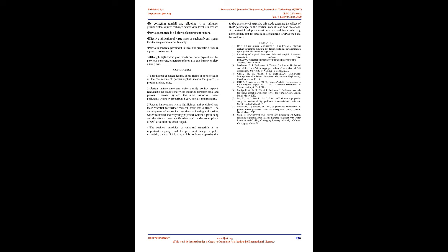Testing methods: the water absorbing capacity, water retention capacity, and compressive strength of hard and water retentive mortar, and the liquidity of the fresh mortar, as well as the rutting resistance, moisture susceptibility, low temperature bending resistance, surface slip resistance, and cooling effect of water retentive asphalt concrete were tested using at least 3 replicate specimens. Objective: 1. To study porous pavement. 2. Planning and designing of porous pavement. 3. Environmental consideration of porous asphalt.